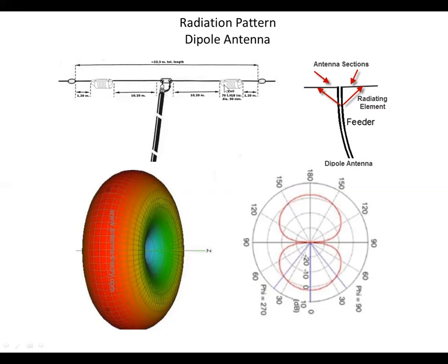And then we have some sort of insulator that will interface between the wire and the rope, and then this rope goes to whatever supporting structure you may have, be it an antenna mast, a tree, just whatever you have up there. That way you have a fixed wire length in free space.